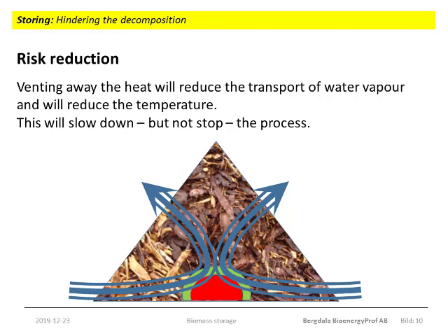The way to do that is to allow cold air from the surrounding to penetrate into the pile at the bottom. The natural draft induced by the heat developed from the microorganisms will provide the driving force for this penetration, and this airflow will then escape again along the steepest pressure gradient and carry with it the surplus heat. So a low and porous, that is a permeable, pile will maintain a cool and low active central part.